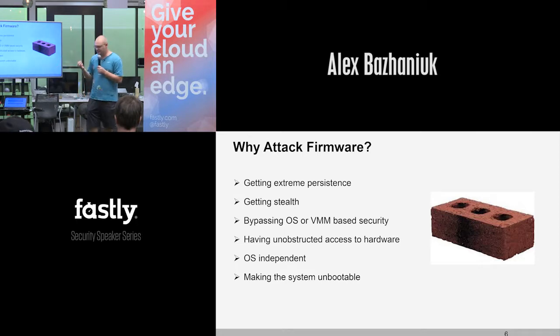Even if there is no vulnerability, the attacker may just find the SPI chip on the motherboard, connect a SPI programmer and overwrite the SPI chip. So in this case, it can be part of a sophisticated attack where instead of going through remote code execution, then local privilege escalation, then compromising the system, the attacker has physical access or somehow compromises the firmware, and the attack goes from the opposite direction, where the firmware infects the operating system, and by dropping a file in the operating system, it also drops a file which may communicate with a malicious backend. So firmware is part of the security scope because it can be really persistent, really stealth, and part of a sophisticated attack.